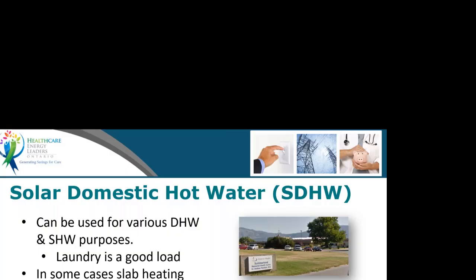Stephen, and if you have solar domestic hot water, you probably should have gray water heat recovery associated with that. So I didn't hear you that, Michelle? It should probably have gray water heat recovery if you've got solar domestic hot water, like you said. That's right. So, exactly. If we're throwing a lot of heat down the drain, before we try to make up for that with a solar system, why don't we look at gray water heat recovery, recovering the heat from that gray water that is going to drain.